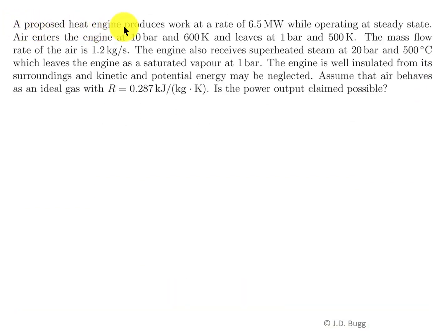A proposed heat engine produces work at a rate of 6.5 megawatts while operating at steady state. Air enters the engine at 10 bar and 600 Kelvin and leaves at 1 bar and 500 Kelvin. The mass flow rate of the air is 1.2 kilograms per second.